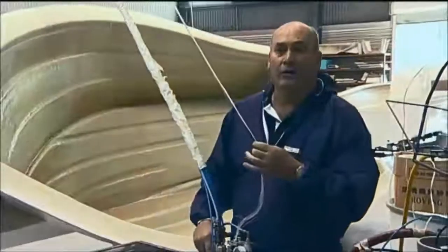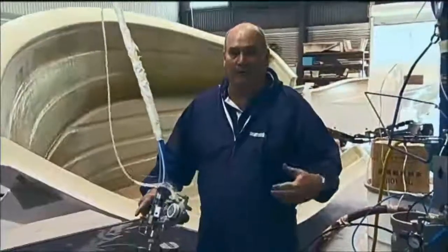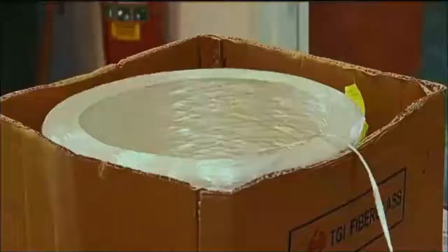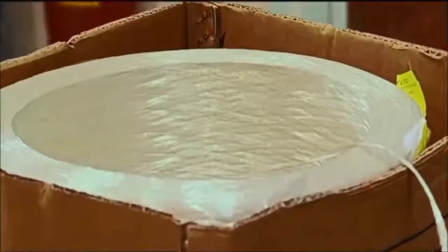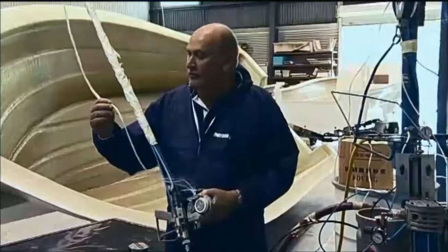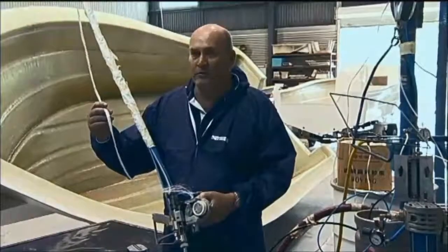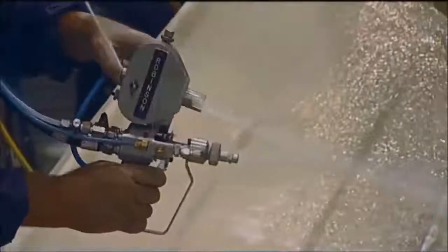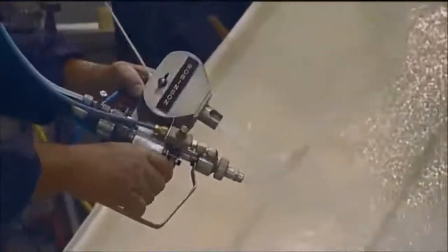What feeds into this cutter head is what's known as continuous roving. Okay. Unlike chop strand mat where we can weigh it per square metre, it's pretty well impossible to do with this system. So what we do, we measure it by what's known as tex, and the tex of this particular roving is 2400. That means it's 2400 grams per 1,000 metres. So if we're to take this out for a kilometre, bundle up and weigh it, it will weigh 2.4 kilos.